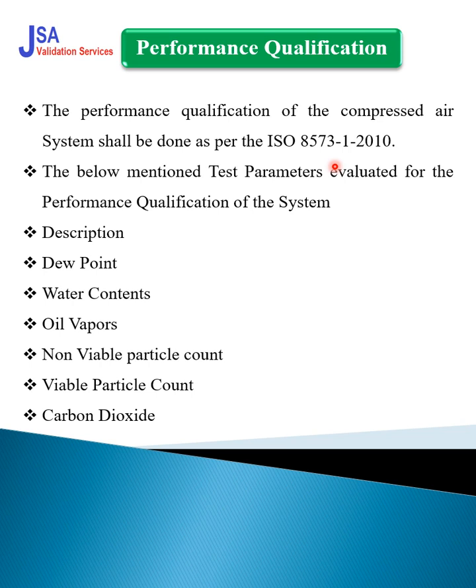So the basic guideline for the compressed air system is ISO 8573. These are some tests that should be evaluated in your protocol, that should be a part of your PQ test plan.